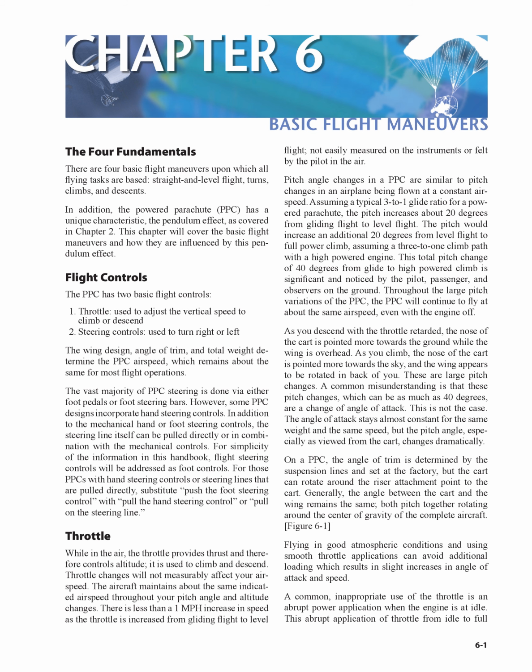This chapter will cover the basic flight maneuvers and how they are influenced by this pendulum effect. Flight controls. The PPC has two basic flight controls. 1. Throttle, used to adjust the vertical speed to climb or descend. 2. Steering controls, used to turn right or left.